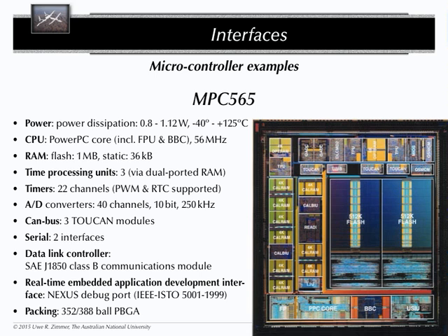Clever, huh? And this is the way you interface the main CPU with these devices via dual-ported RAM modules, which are twice overclocked, to provide this kind of complete independence in terms of free-running real-time devices. And this gives you an idea how serious people are working on these real-time devices, that they're going to this length to guarantee that you will actually have free-running real-time devices which cannot physically be disturbed. You have no way to get this out of whack by whatever you do when interfacing with these devices.